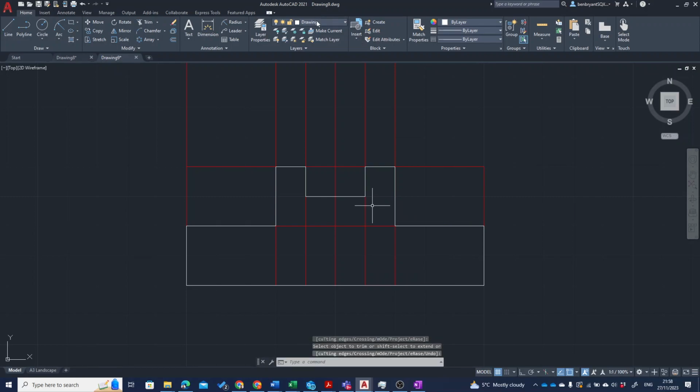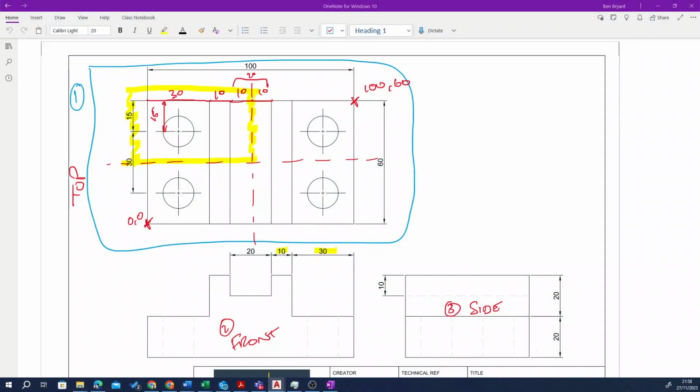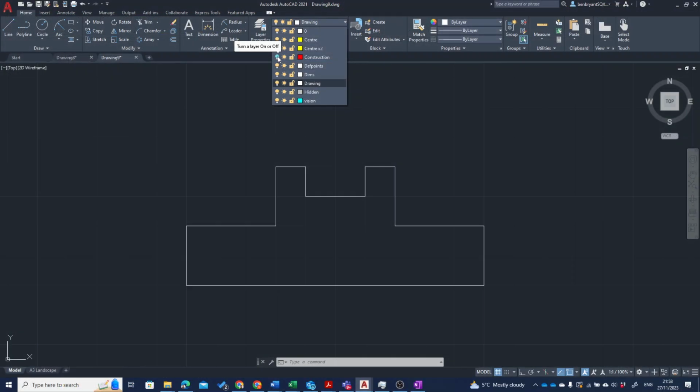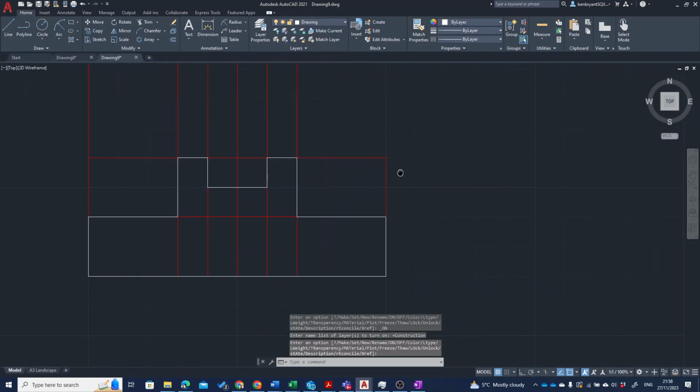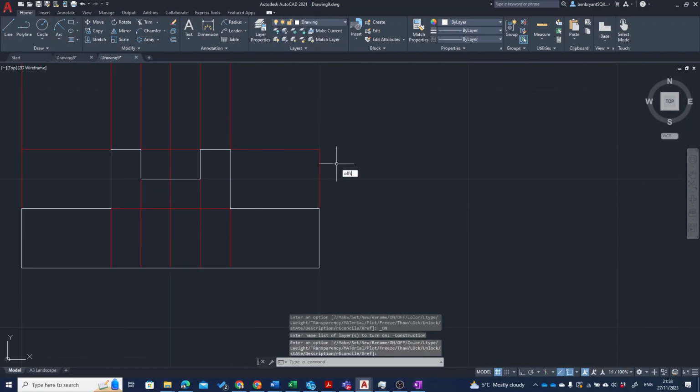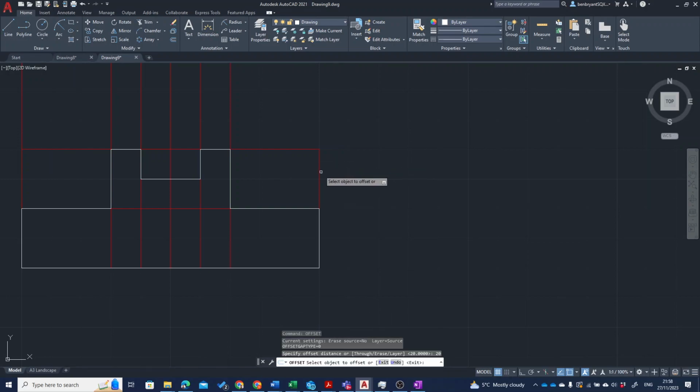And there we go. If I turn off the construction lines, I've got that element of my shape. Like so. So last one to do, I'm going to do possibly a 20mm gap between the edge shape. So I'm just going to drag this along using the same reference point again. I'll do 20 because I can always add 2 to make 40 if it's not big enough. Fine.